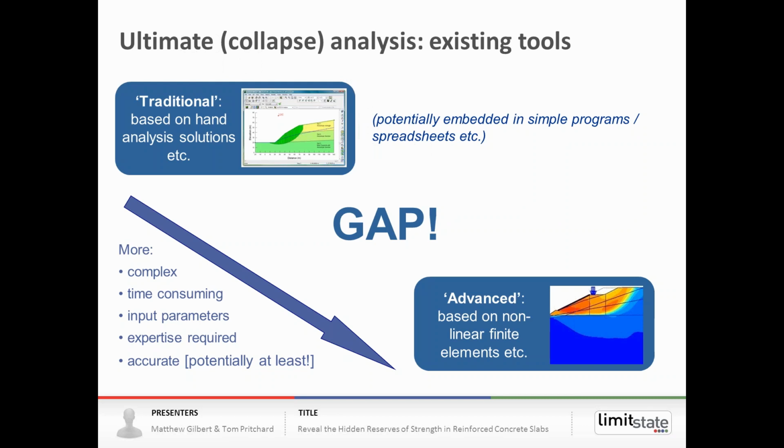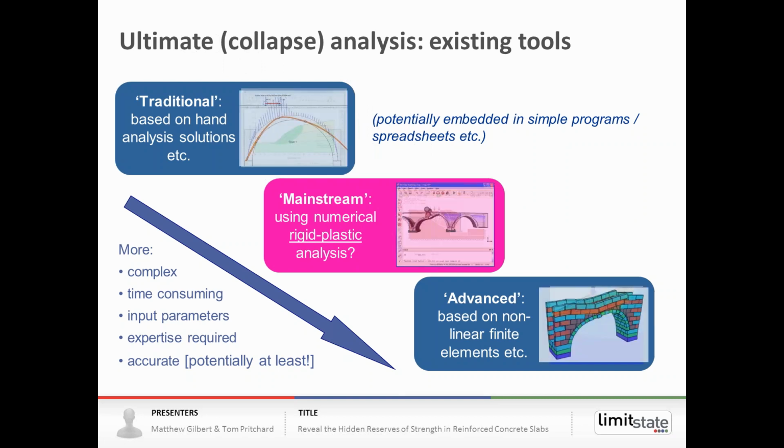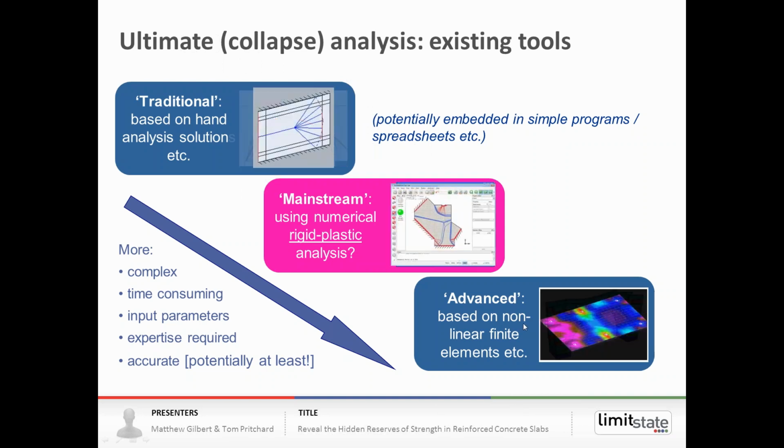And traditionally, you then had to move to much more complex, advanced tools such as finite elements, etc. What we've been focusing on is actually bridging that gap with a range of mainstream tools based on rigid plastic analysis techniques. We could be talking about a geotechnical application, as you can see on screen here, or we could be looking at a masonry application, in this case a masonry arch bridge, or clearly of interest today, we could be looking at reinforced concrete slab analysis or design.